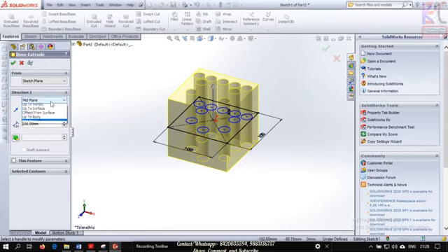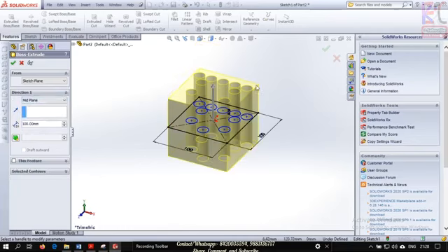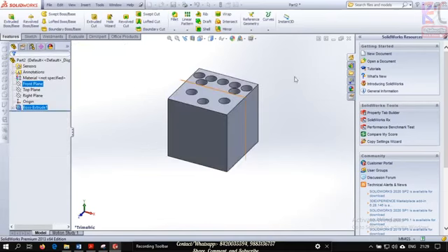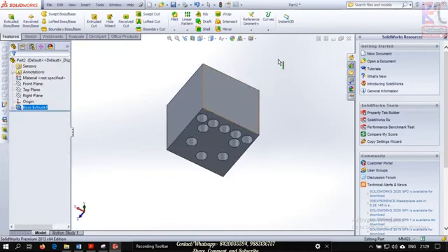So you could do anything. I could go for blind for now. It's not mandatory to take blind. You could also take mid plane. Mid plane is taken to show the symmetry. It looks good, and it's very good for our technical purpose also. Fine. Right click. Just right click over here. Now you can see what you have made.